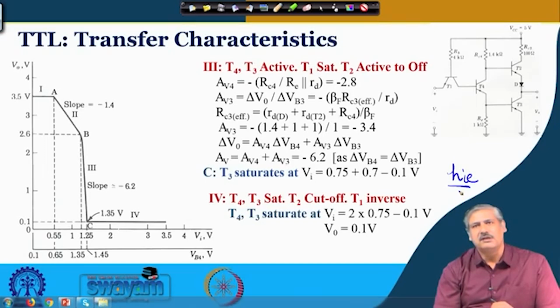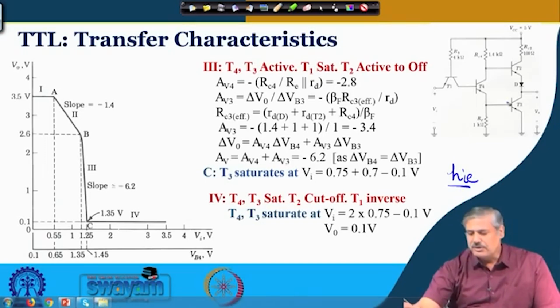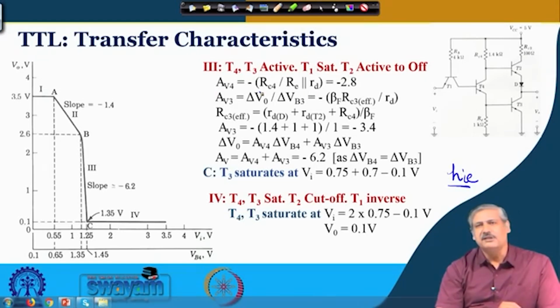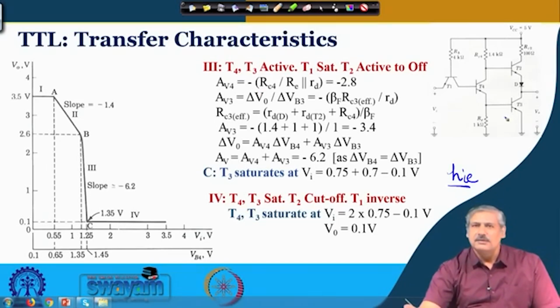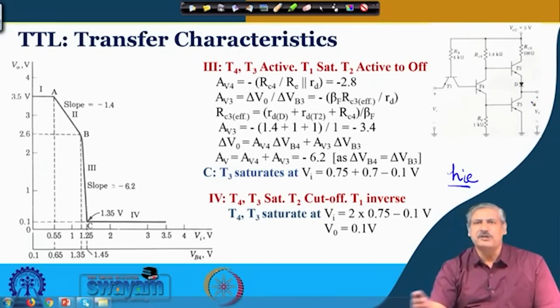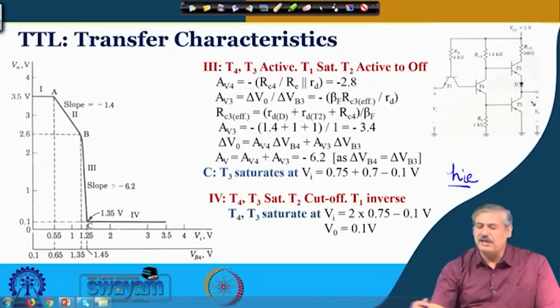2 port representation. So, this resistance will come in parallel with RE, and because of which this gain will become RE parallel RD in the denominator and RC4 in the numerator, and RD is of the order of 1 kilo ohm, similar to this. Of course, the more current flows, we know the current versus voltage curve, by which at higher current the RD value will come down.